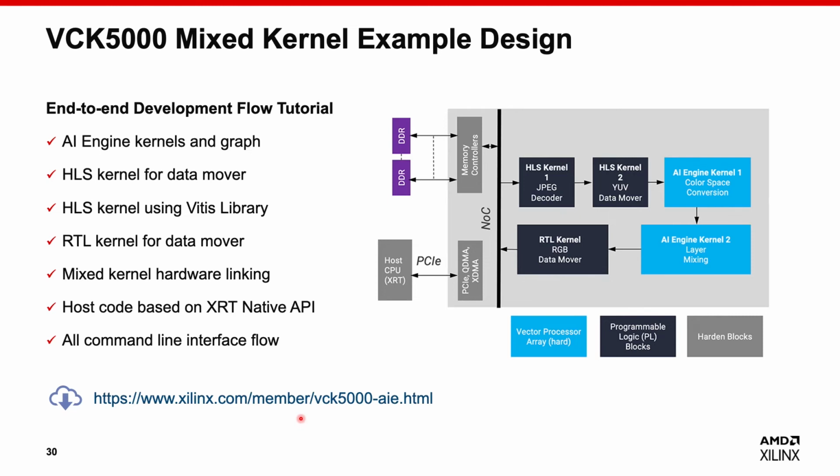The content includes AI engine kernel and graph programming, HLS-based data mover kernels for AI engines, HLS kernel design with Vitis accelerated libraries, RTL-based data mover kernels for AI engines, mixed kernel hardware integration, and host application programming based on XRT native API.